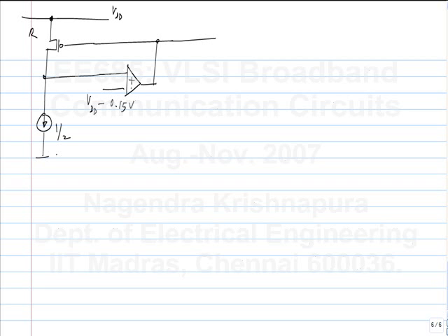Why is that? So, there is an inversion through the transistor, or if you break the loop here, everyone knows how to do this, right? Okay, I do not have to go through this. So, there is an inversion here, you do not need an inversion through the op amp, okay. And this control voltage can be propagated to everything.